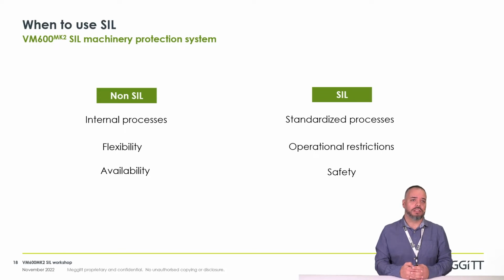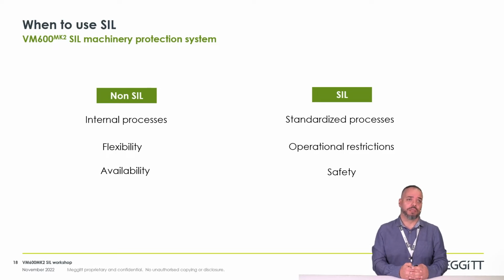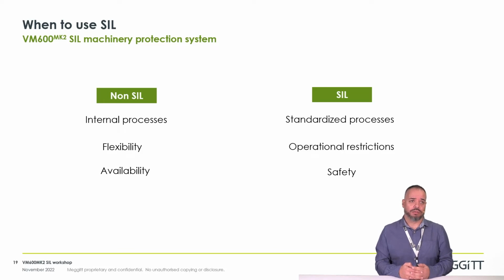Of course, a safety system must have good availability. However, its primary focus is on safety. So, as it will include many more internal diagnostic measures, availability will be sacrificed somehow. The spurious trip rate is directly related with the extension of internal diagnostics in the equipment. A non-SIL system is typically less complex and with less internal diagnostics, so it will have eventually a higher availability. For example, a non-SIL system will continue to operate even if some functions are slightly degraded, but for a SIL equipment this is seldom accepted.